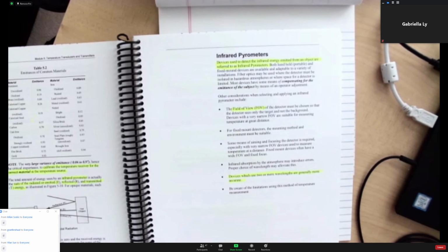Just like if you have a resistor in a circuit and you try to use the ohmmeter to measure the resistance of that resistor, you're probably not going to get a very accurate measurement, because there might be some other resistor in parallel with it. So if you want to actually test that resistor, to measure it, you have to disconnect it from the surrounding circuit. So that's another basic thing I think you should know as an electrician.